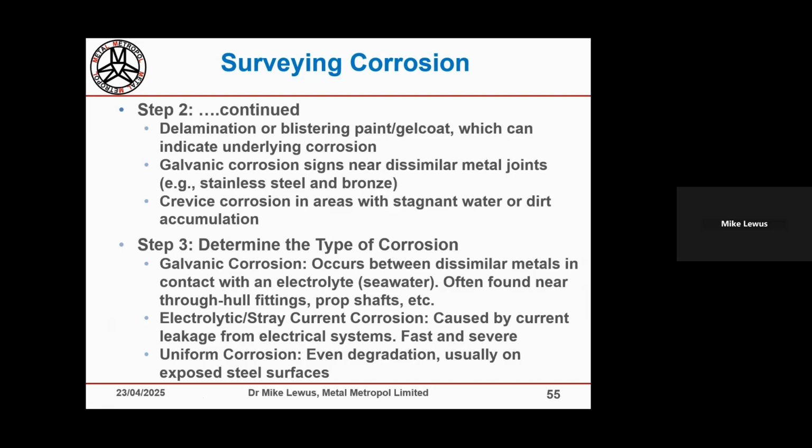But sometimes you have to make some sort of objective measurement, or attempt to, on how deep the pits are, how extensive crevice corrosion is between flanges, say on pipe work. You may not even see the crevice corrosion because you might have to dismantle the pipe work and look on the flange faces to see any of that.